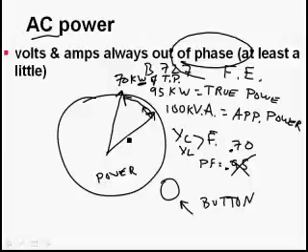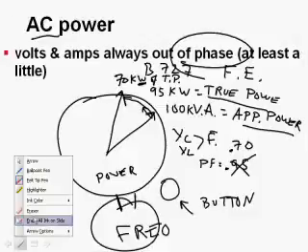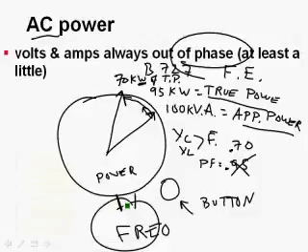So as soon as you see that the difference between true power and apparent power is greater than that 5%, the very next gauge you're going to look at is the frequency gauge. And if here's the green arc, oh, I could draw a green arc. Cool, man. If here's the green arc, and right smack in the middle of it is 400 hertz, then my